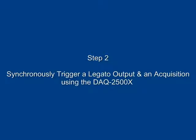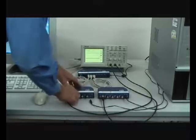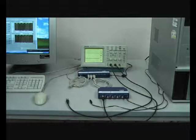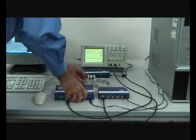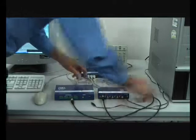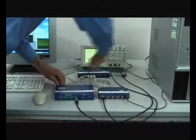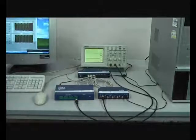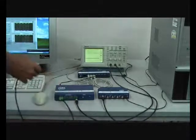In step 2, we will synchronously trigger a Legato output and a data acquisition using the DAC 2500X. Firstly, replace one of the Legato modules with a DAC 2500X module. We can use the same USB and power cables. Connect the output of the Legato to the input of the DAC 2500X.